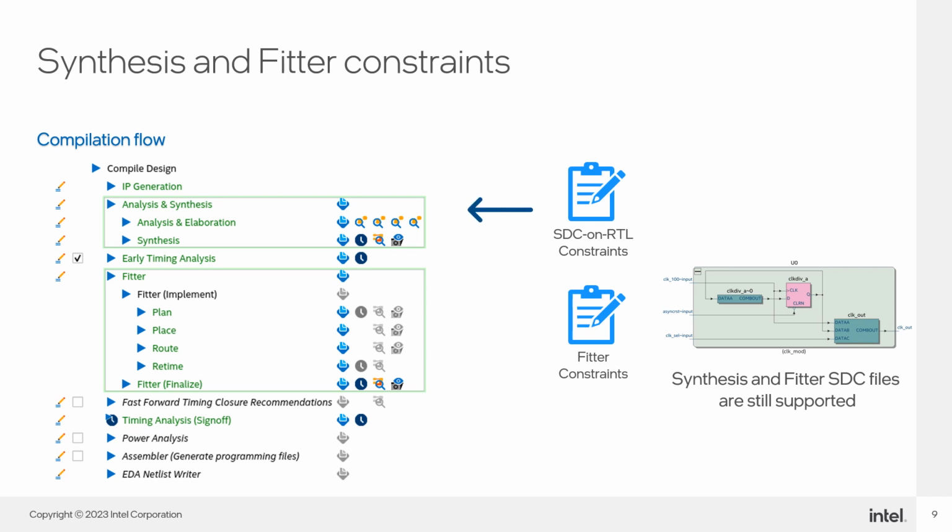But there's more. You retain the capability to target nodes from the compiler-generated netlist of synthesized nodes to incorporate additional SDC constraints, thereby complementing or overriding constraints defined via SDC-on-RTL files. This further refines your timing analysis, resulting in even more precise results.